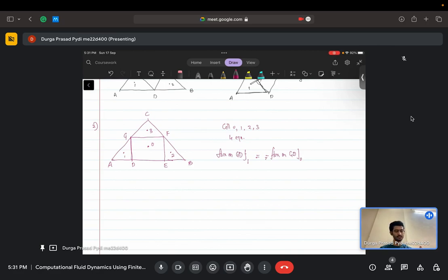So the first step we do here is calculate the fluxes on each and every face. Once we get all the fluxes on all the faces, then we write the cell balance equations. That could be the way if you are actually implementing in the code. If you go cell by cell, then each time you are evaluating each face value, so you are actually doing it twice. To prevent that, you can first calculate the fluxes on each face, and then frame your equations and then solve them.